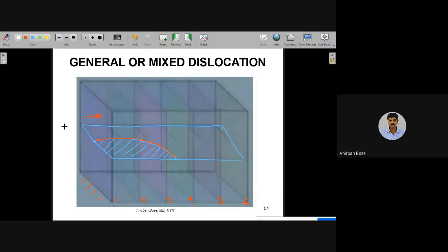Okay, so this is say H and this is say F. So this is the line around which the defect will occur, and exactly at H. So what is the dislocation line vector now? Remember, dislocation line vector will be tangent to this line. Previously, it was very simple, along EF or along GH. That was the dislocation line vector because they were straight lines. But now it is a curved line. So dislocation line vector will be tangent. So at point H, maybe this is the dislocation line vector T.